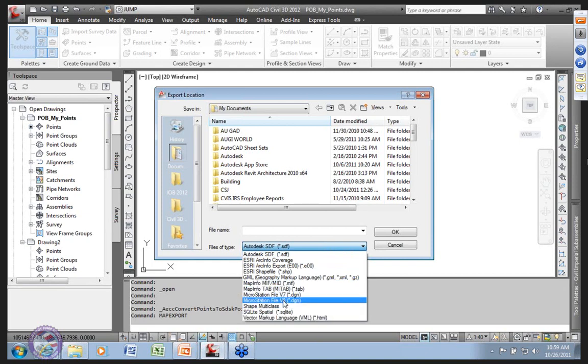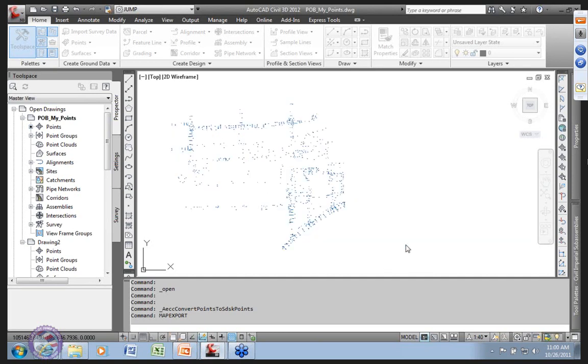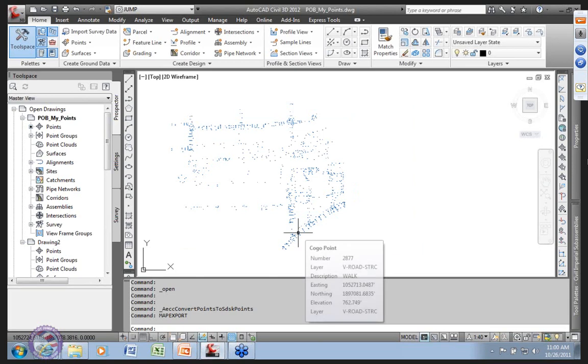a MicroStation V8 file, okay, and it helps to have all the seed files and all that stuff, but pumping it out to DGN really isn't any more difficult than going out to AutoCAD. That's one way to do it. The other way to do it is produce the AutoCAD output and then go over to MicroStation. You will probably find it faster and easier than doing it direct out of Civil 3D.